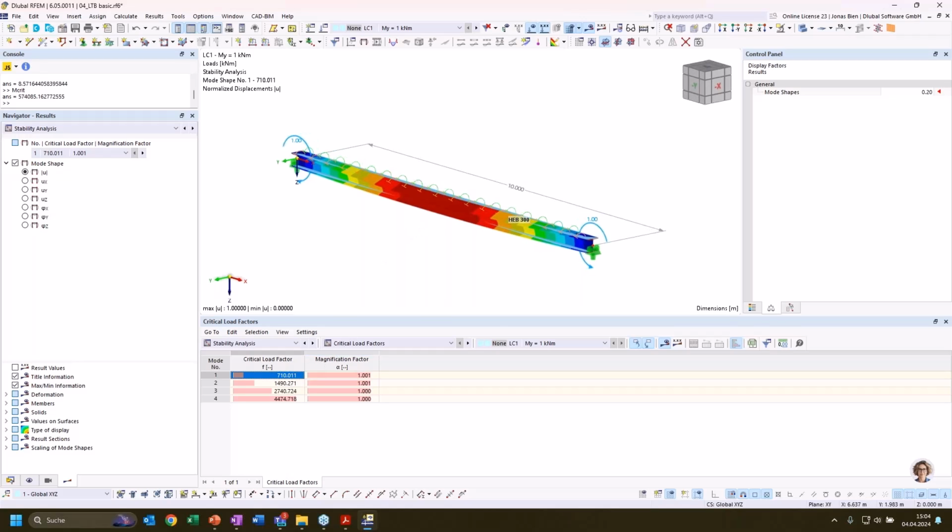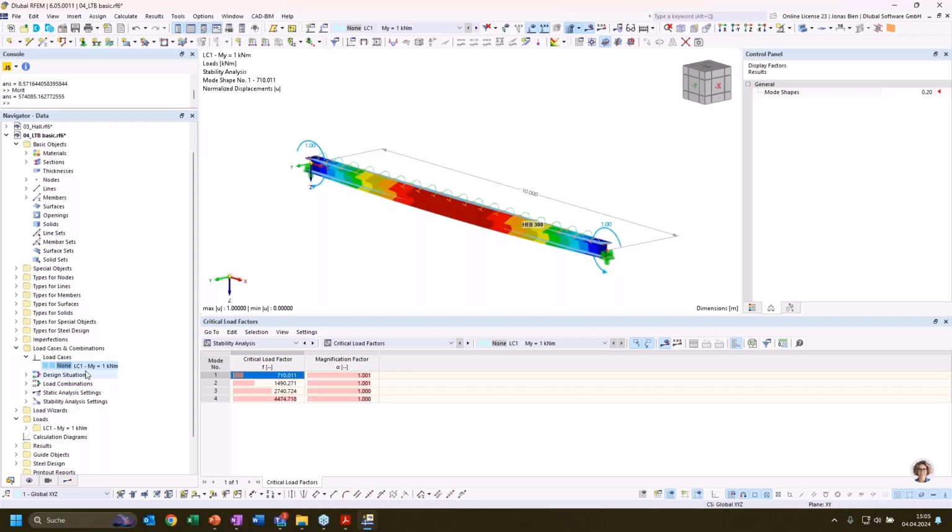because you may want to perform a lateral torsional check, like using a second order theory analysis with imperfections, and maybe you want to also have these rotational restraints be effective in this global analysis. So that's why we added this option through the structure modification.